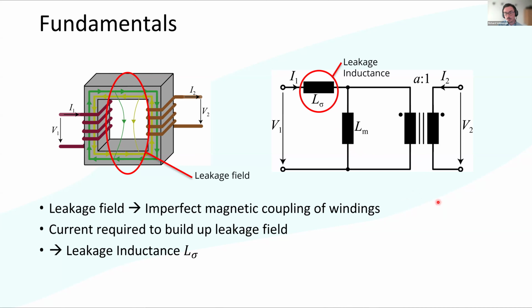And you can measure those separately. And you always measure from one side and short circuit the other. So this is the general concept. And another thing you have in reality is that from the short circuit, you also sometimes create loops. And this loop adds to the inductance measurement, but it's actually not part of the leakage inductance.